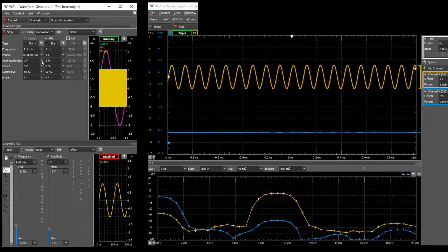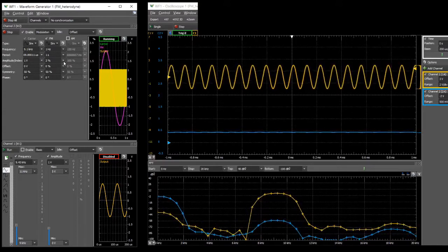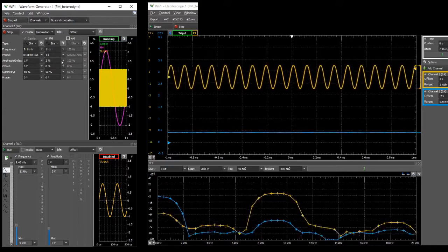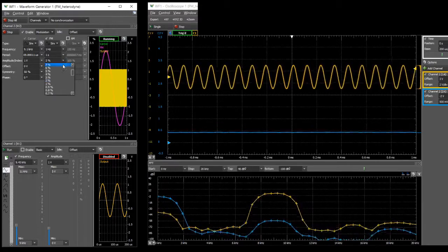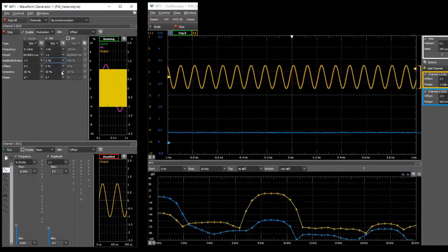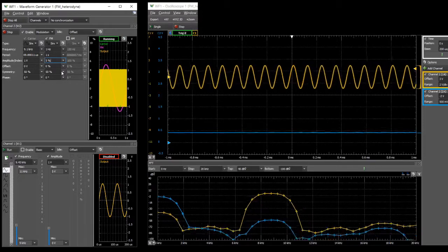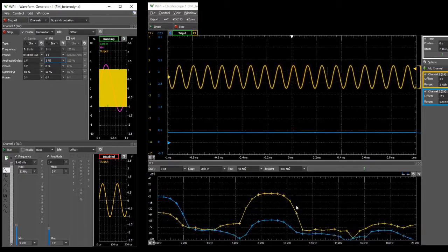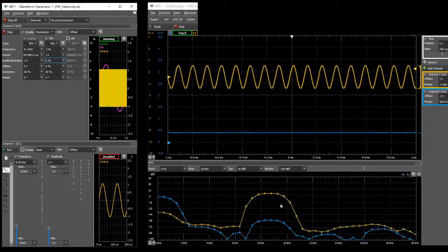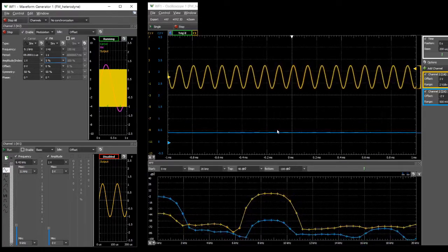The frequency modulation rate, that is, how fast it changes, is the data transmission rate, while the frequency modulation amplitude indicates how much it changes. The larger the frequency changes, the easier to see, which entails the higher resolution of the data level. Sure, but all advantages come with costs, as we will see.